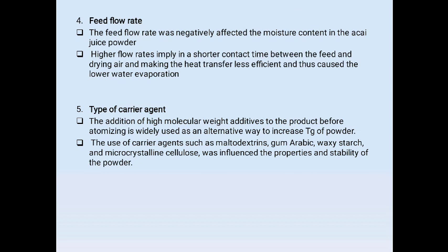Feed flow rate. It negatively affected the moisture content in the acai juice powder. Higher flow rates imply a shorter contact time between the feed and the drying air, making the heat transfer less efficient and thus causing lower water evaporation.